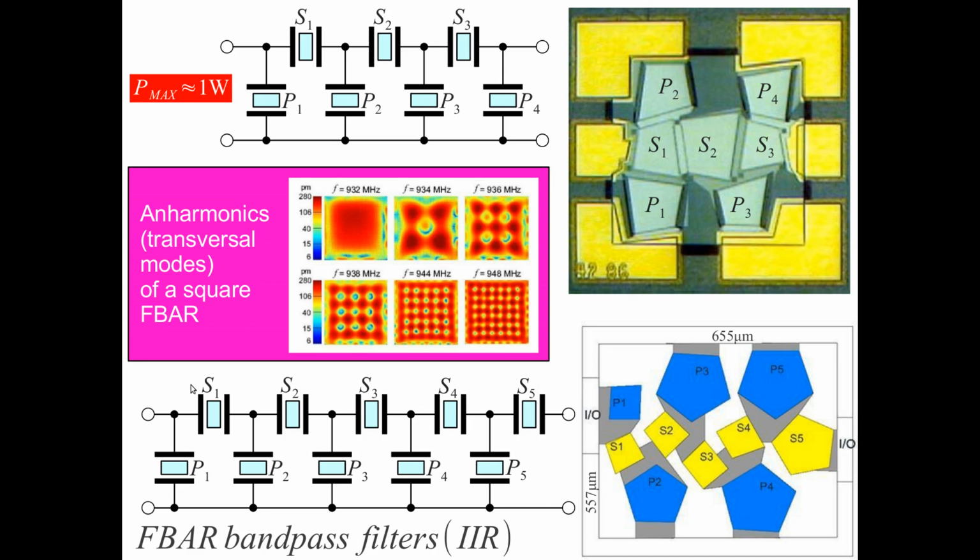These filters are usually built as ladder filters, where you have series resonators and shunt resonators. These are chips actually less than a millimeter large. They can be integrated into chips so that they will fit inside the mobile phone. These are much smaller than electrical cavity filters.